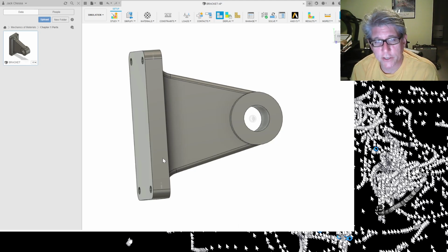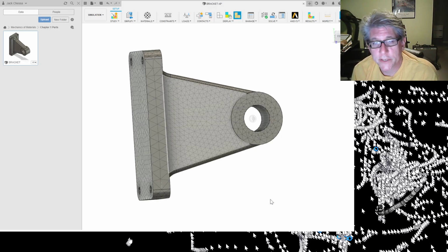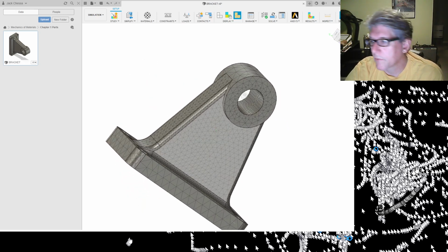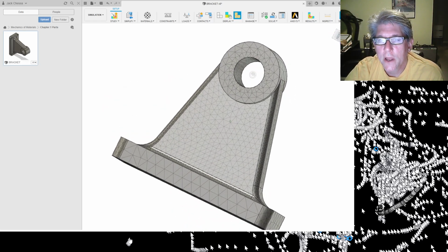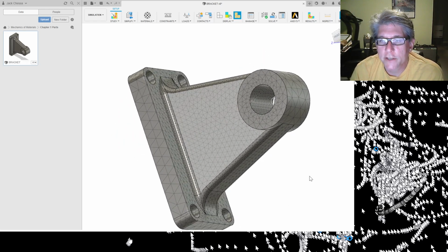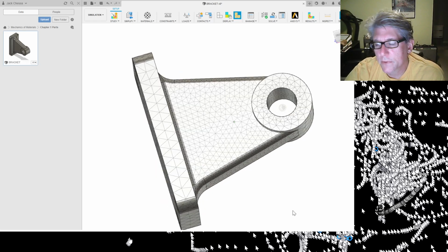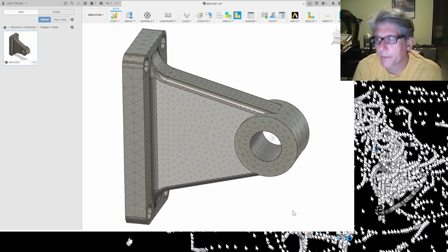And let's mesh it and see what it looks like, okay? So we're going to generate the mesh. And there it goes. So it gives you some stats. There's very much an art to meshing. It does have a very significant impact on your results, but again, I'm not going to get too much into it. But this is pretty reasonable, right? So we want to analyze the stresses in this region and a little bit in this sort of contact area, and from my experience, this probably is more than good enough with parabolic elements.